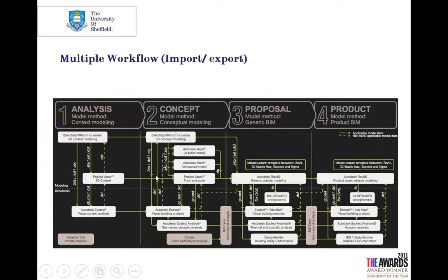And it's an import-export. So, for example, here you would have to export a DXF file. Then you'd have to import that DXF file. Then you'd probably have to fix it. Here you've got GBXML export into Ecotect Analysis. So the software are linked, but they're not integrated.